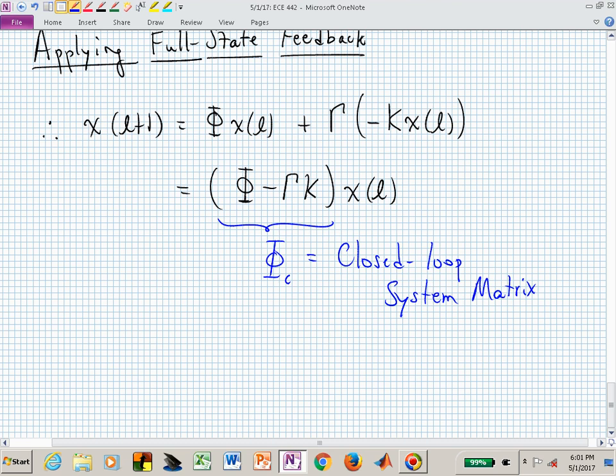So if that 2 mode gets excited in some way with a disturbance or some kind of offset, it's going to grow unbounded. Now what we want to do is have somebody walk up and kick this system, phi sub c, and it's well behaved. So we'll kick it again. And it's well behaved because it has poles at 0.8 plus and minus j 0.2, and those are inside the unit circle.